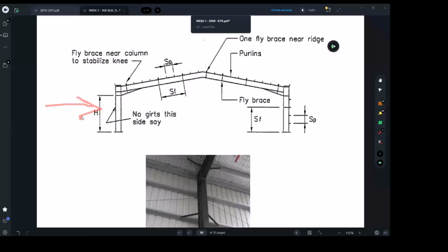Talking about wind loads and portal frames, they're going to have rigid connections, fully welded, or you're going to go through all those detailings in terms of construction. Same thing here, same thing there. The moment connection will allow the frame to resist flexure, and you can't actually push it. Unlike the situation if you just had a pin.